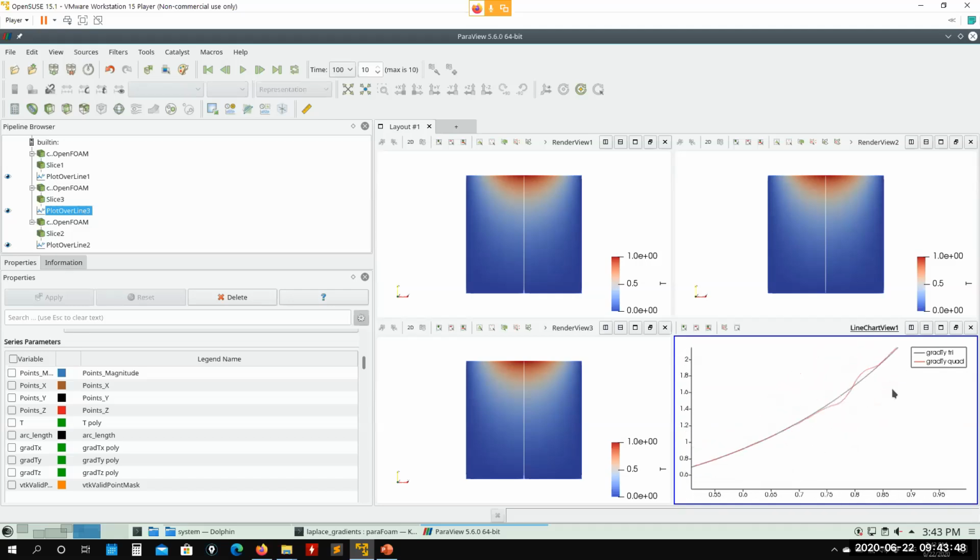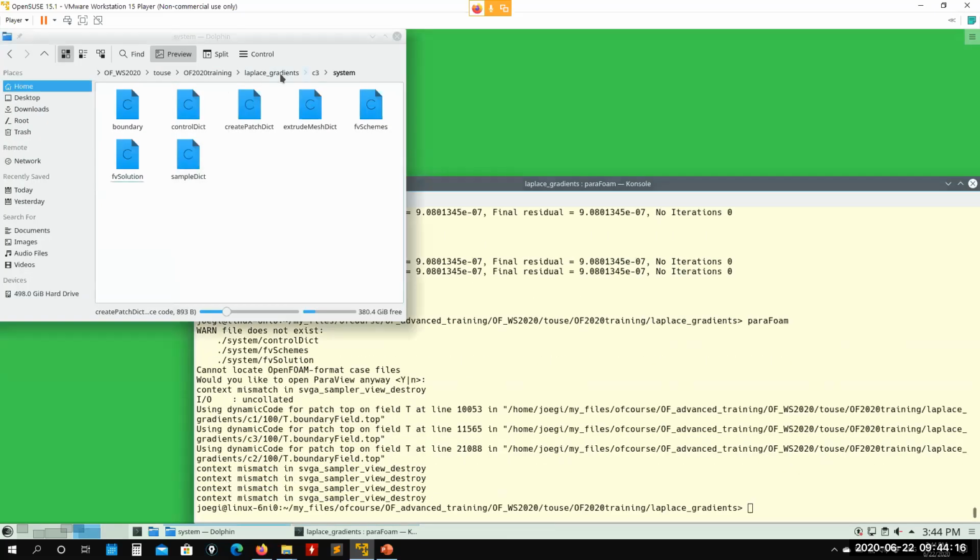See, by just adding the right discretization and improving the gradient, we have better gradient computations. As you see the other one, okay, this one. Look at that, the previous one was something like this, very oscillatory. Even if your solution is the right one, you have something in the background that sooner or later might influence your solution. So my advice also, be careful with the gradients. Particularly, they are very important.